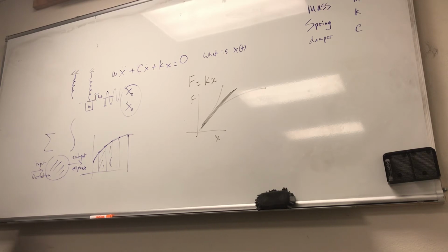And then you got the soil underneath. So this is your physical system. And you know what's going to happen as this mass comes in and hits this anvil. What's going to happen? And then you go like, I remember from dynamics, that's impact, right? So as they do that, depending on the coefficient of restitution, the anvil is going to have a post-impact velocity, right?